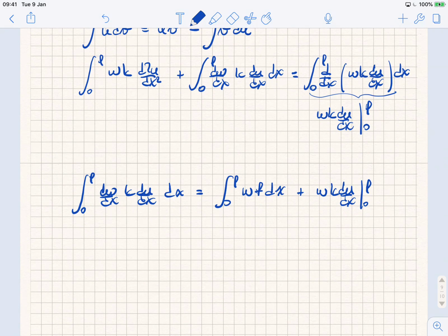Right, and if you remember, this guy here was actually defined as our heat flux. So from this expression you can again say that this can be defined as my bilinear form, and this whole thing is my linear form, right? Because even though this guy has a dependence on u, that's actually something we know, that is the heat flux, okay?